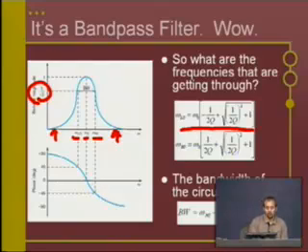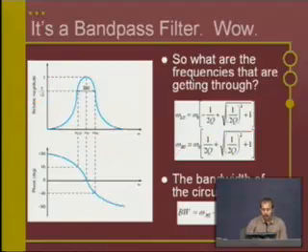And so where the gain or the magnitude passes through that point, that's where omega low and omega high are defined, straight across that line. Quantifying what those look like are these formulas here, which basically, if you know what the quality factor is, you just plug it in here and run the formula. Where they came up with this, I have no idea, but this is how you can calculate the half power frequencies.